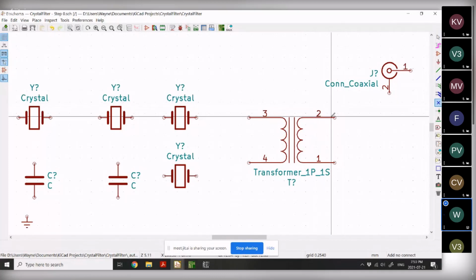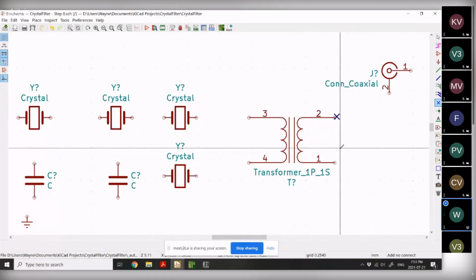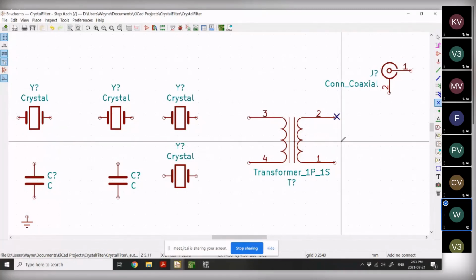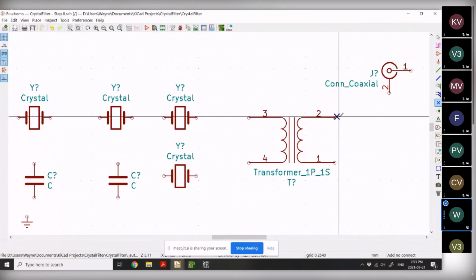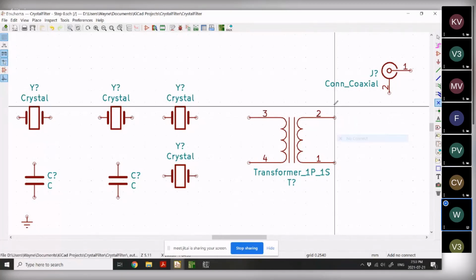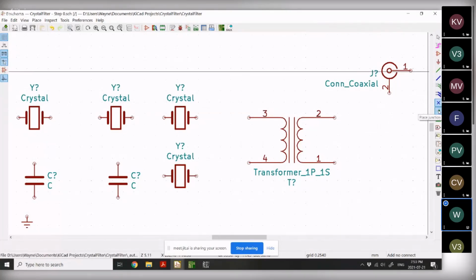Now what that is: if there is a component on your board that doesn't need to be connected, and typically you're talking about the pin on an IC that's not used in your design, like a microprocessor if it's on your diagram. You might be using one pin of a microprocessor and leaving all the rest of them off. You put a little marker like that on the page and it tells KiCad that it's intentionally left unconnected. Don't give me any errors. Please don't bother me about it when you move to the diagram. All right, so that's that. And the final thing that I might use is place a junction. You normally don't have to do this because you can make junctions when you're drawing wires.